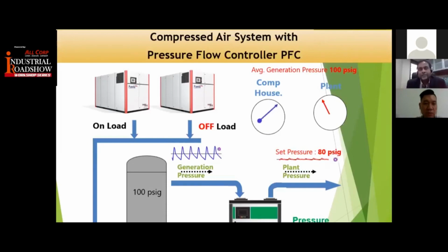To measure the harmonics level, of course, you need to get the right people to do the harmonics level measurement. If your incoming neutral cable temperature is hot, when you touch it, it's very hot, you roughly know these are the symptoms of harmonics present in your plant. So you have to quickly do a harmonics level measurement. The other thing is, if a lot of electronic equipment in the plant keeps on failing, like a controller failing, BMS system failing, and tripping of your breakers, this is all caused by a high harmonics level in the plant.